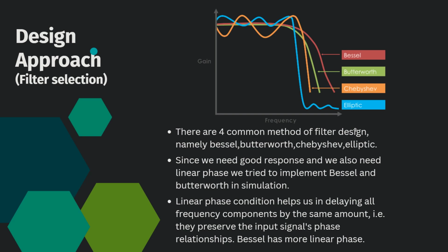The same thing with the minus 3 dB of the high pass. Like we got around at 100 hertz, we got like minus 3.73 dB. And the images at the DSO show us how the attenuation is there in the 900 millivolt and 1 volt. As you see, at 80 hertz we have 900 millivolt, and at 50 hertz we have 1 volt, which is the same signal.